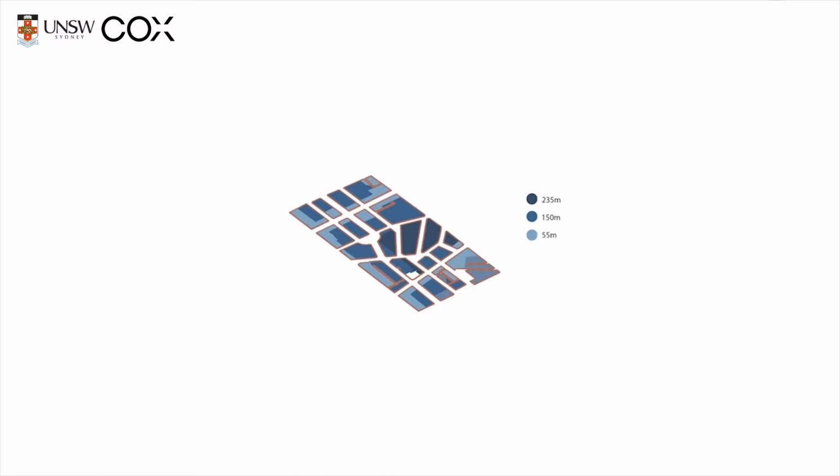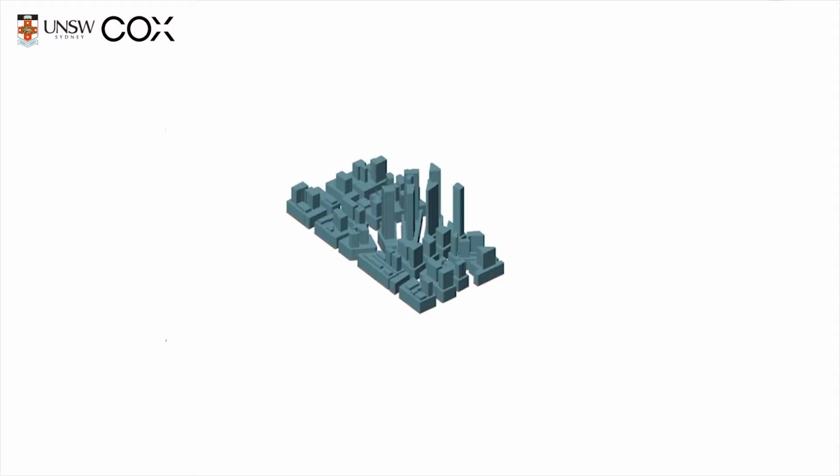We know the right height of building for each, and just with that, you can make a really basic building envelope. So what we did was we got the property, we extruded it up to 45 meters of height, then we set back each face according to the DCP, and then cut it off once it reaches the maximum height determined by the HOB.